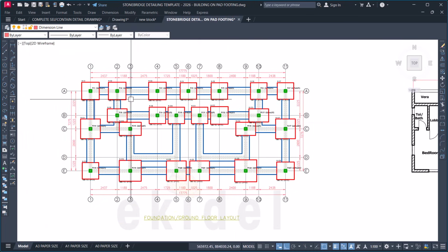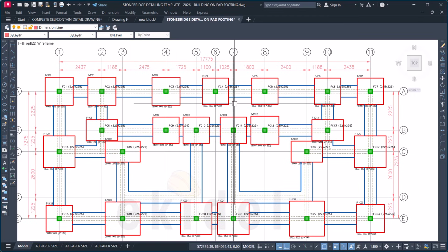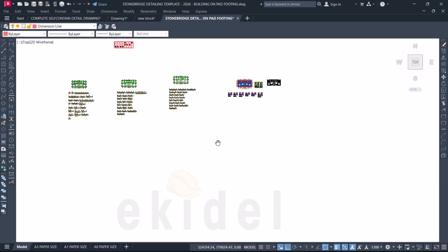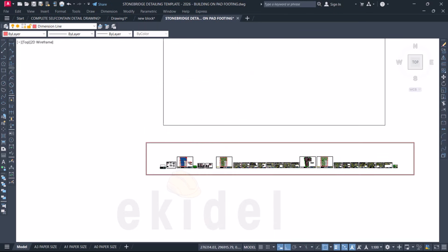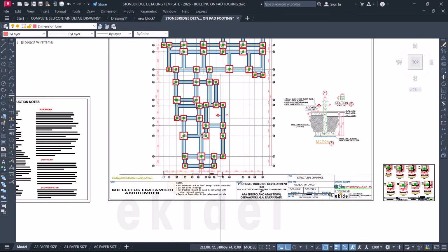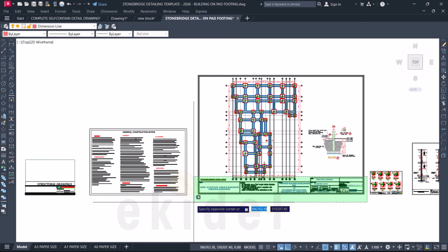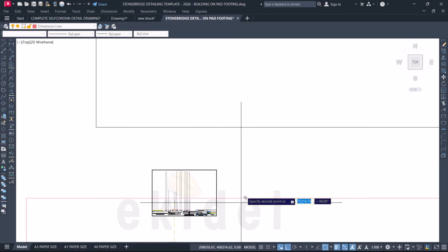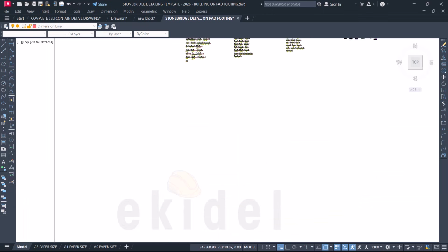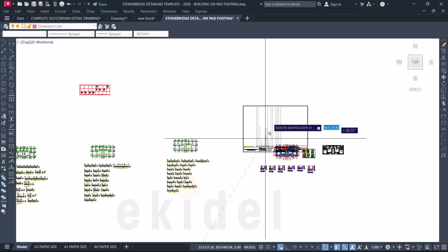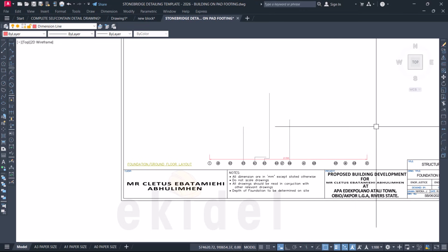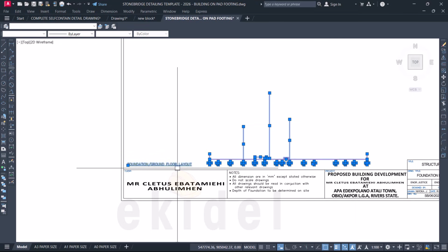Now the next thing I can see is that we have not done the dimension for this. Okay, that's fine. The next thing now is to put this drawing in sheets. So I'll come now and copy a sheet here. Copy this sheet. I'll come now and copy this title sheet here. Copy it like this first. CP or CO, copy this, and then come here, turn off my snap, paste it somewhere here first, and remove everything that came here with the copy. Like this one should go off, this one also will go off too.